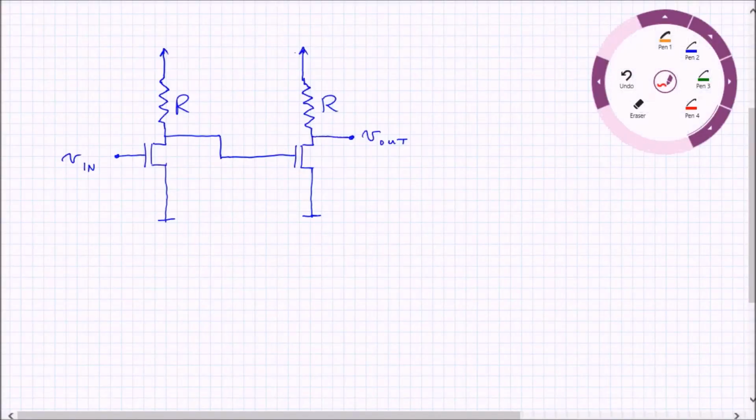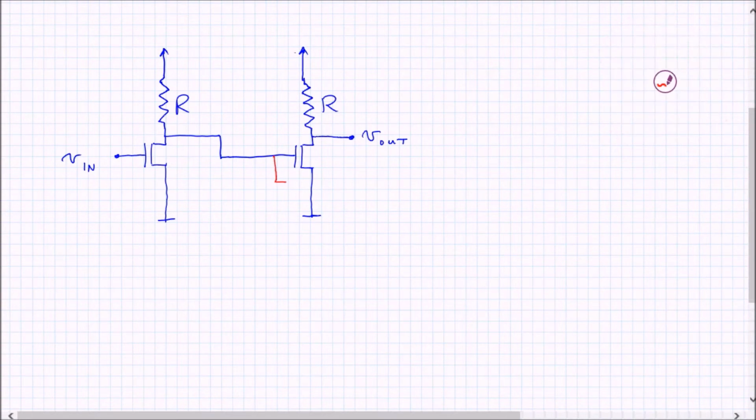In this circuit here, there's three elements that are contributing. The two that are creating the oscillatory behavior are this capacitor and the inductance, the parasitic inductance of this wire. And so basically the circuit that is oscillating starts up here, goes through the power supply, then comes down through the ground, through the inductor and back. And that's the RLC circuit that results in this oscillatory behavior that we're seeing.